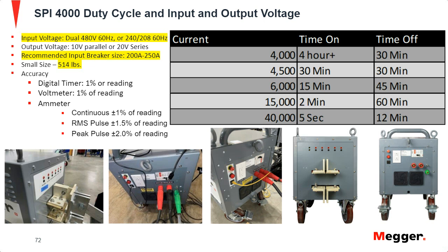So when you test low voltage circuit breakers, you're doing an injection test to verify the long time, short time, and instantaneous, and also the ground fault, and comparing it to the breaker curve. Whereas timing a circuit breaker contact is usually applied in medium voltage and high voltage circuit breakers. You want to see how quickly the open time is and how quickly the close time is. Low voltage circuit breakers are totally different, so contact timing wouldn't apply for a low voltage circuit breaker.